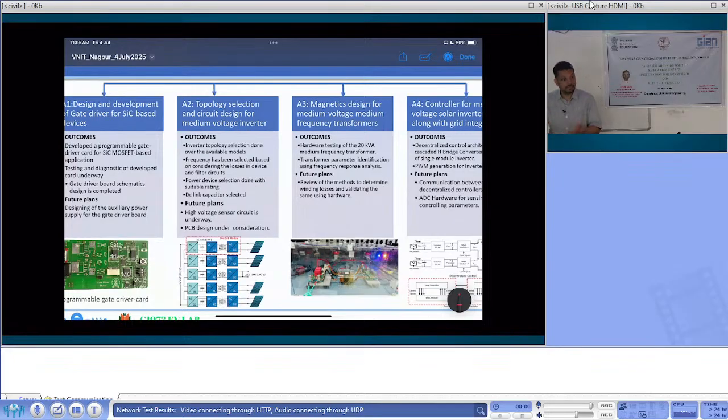But whenever we make the buck converter for the first time, it doesn't work. And over a period of time, you learn the problems. Maybe soldering is not correct, how to actually design the transformer. So a lot of practical learnings happen, and then we know, okay, now we can make a buck converter confidently. Same way, silicon carbide is a relatively newer technology.